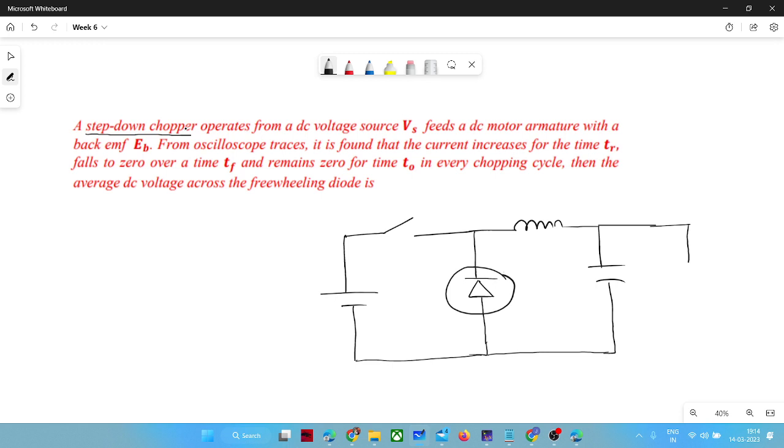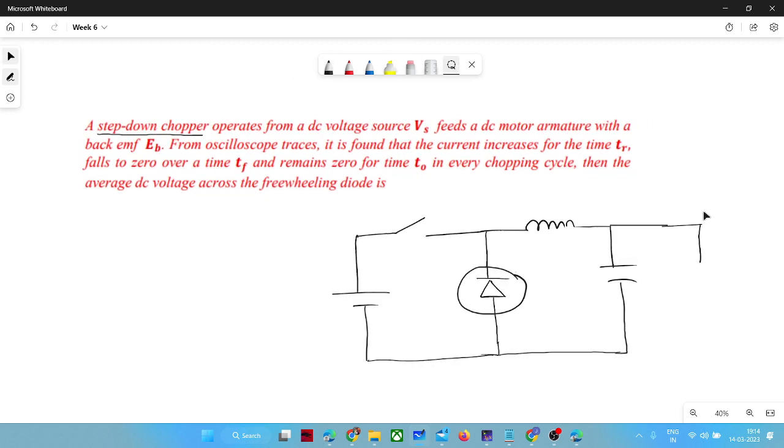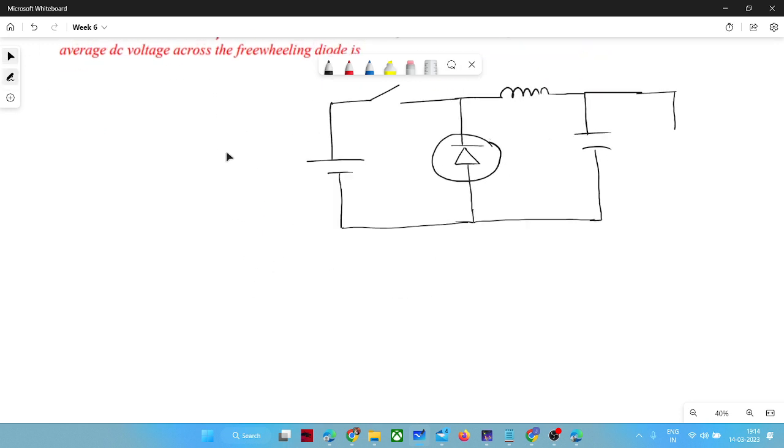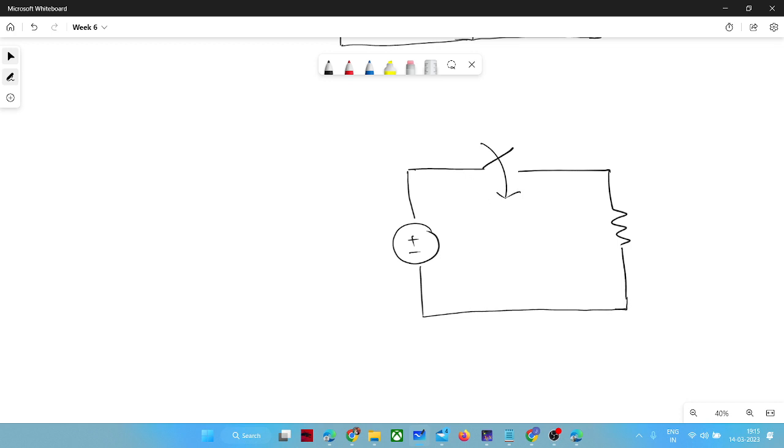That might be you talking about class A, class B, where also step down will happen. Are you referring to those kind of things? No, sir. A simple voltage source with a switch like a MOSFET. Voltage source in series with the MOSFET, and then the output load will be connected. Then also at the load we'll get the decreased voltage. Okay, you are correct. That is nothing but the same thing. This is also a type of step down chopper, just the more practical way. Otherwise, it is a very crude way of drawing the circuit. Yes, you can say that it is a step down chopper.